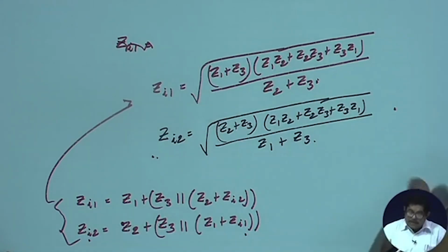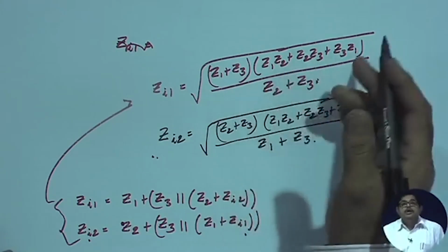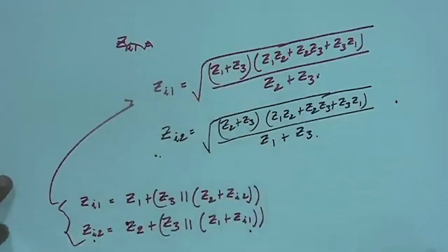Now, always we won't be knowing Z1, Z2, Z3. As I said, let us consider the two-port network as a black box, but we can do measurements and always find these image impedances. How? You know that any measurement requires either an open circuit or short circuit of one of the ports. Also, if you want to find any two-port parameter, you need some port condition, either short, open, etc.